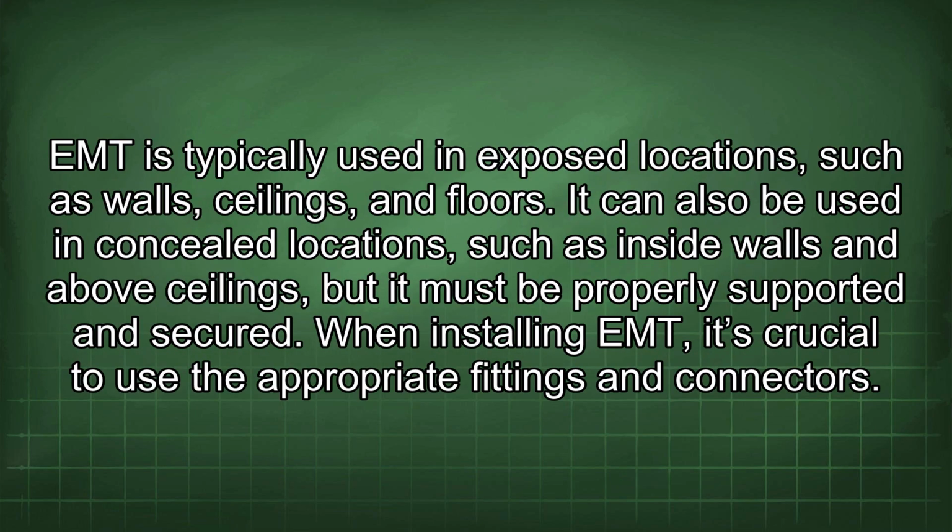EMT is typically used in exposed locations such as walls, ceilings, and floors. It can also be used in concealed locations such as inside walls and above ceilings, but it must be properly supported and secured. When installing EMT, it's crucial to use the appropriate fittings and connectors.